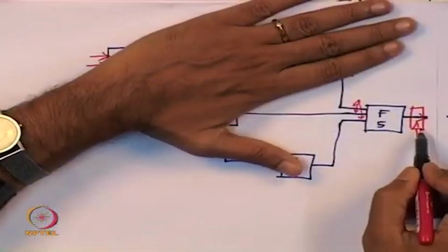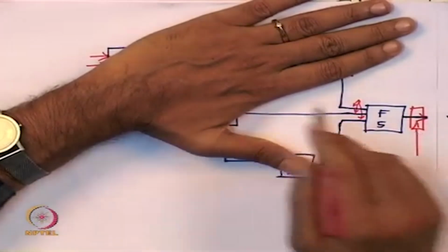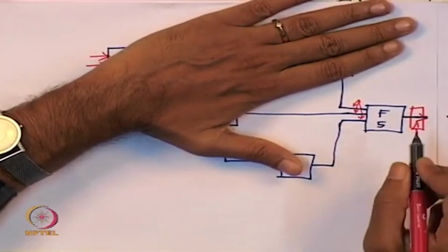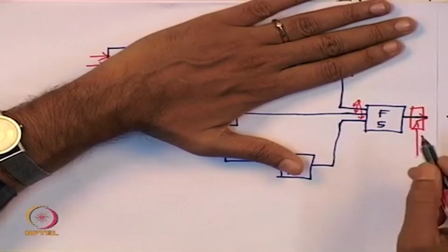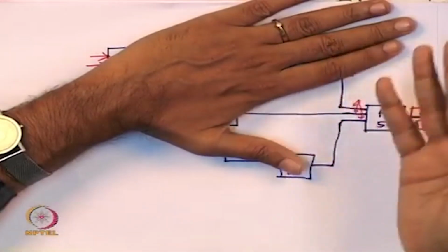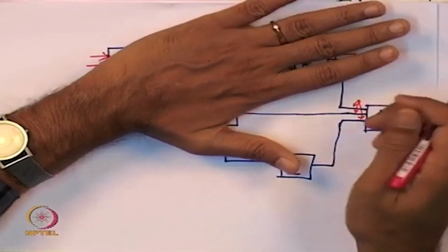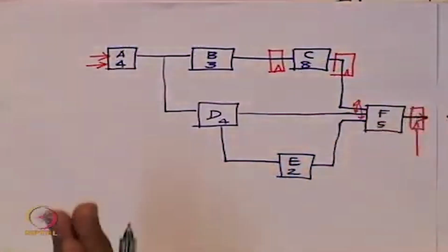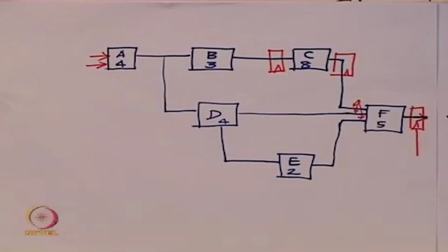For a while, if I put only this flip flop, it will be a one stage pipeline, and a one stage pipeline is not quite useful. It will still have a latency of 20 nanoseconds, so it is not making anything better. So when you are looking at pipeline circuits, you are asking for either a 2 stage pipeline or more.